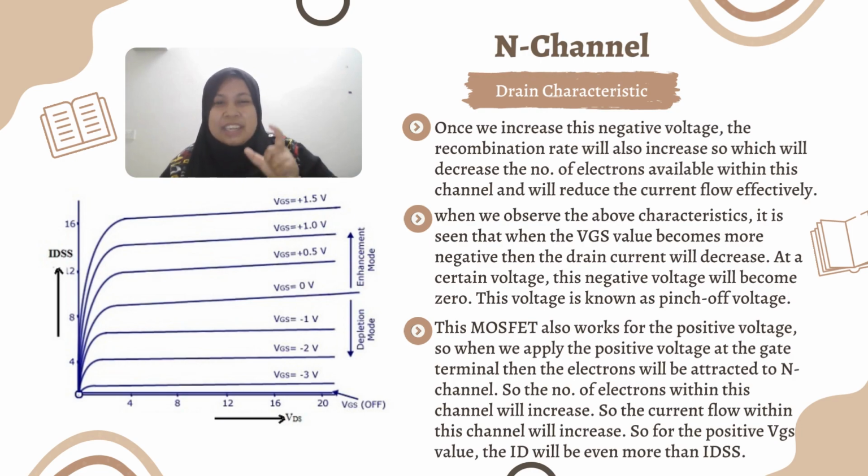When we observe the above characteristic, it is seen that when the VGS value becomes more negative, then the drain current will decrease. At a certain voltage, the drain current will become zero. This voltage is known as the pinch-off voltage.